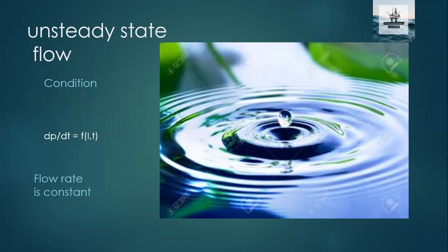So during this travel, if you start collecting water, like in our example, I'm telling water, probably if the same thing happens inside our oil reservoir, you are collecting oil. So if you start to collect oil during that particular time, where the first ripple started to move from the well and until it reaches the outside of your boundary, that particular time period is considered to be unsteady state flow. Once this ripple touches the outer boundary, all the ripples that have been generated one by one before this first ripple will stay static for some time. That is considered to be steady state flow.